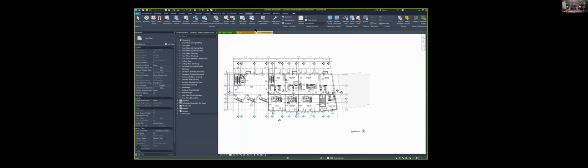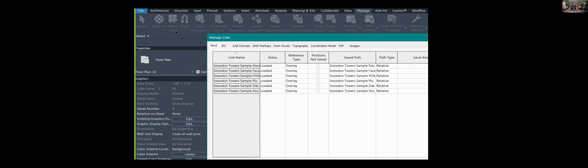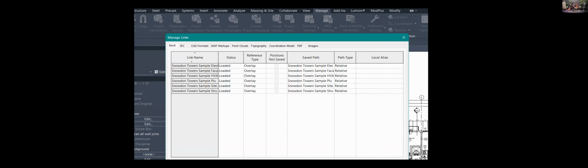Now, if you want to see all the links in your file, then under Manage, you would go to Manage Links. And in the question that I gave you, I said model links, but there are different kinds of links that you can put into Revit. For example, you guys focus more on the model link, which is Revit files. But just like the other group that was doing detail lines, detail lines have a cousin called detail components. So linking a model has a couple of cousins.